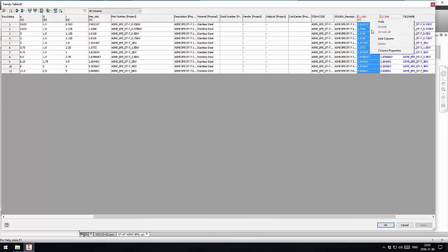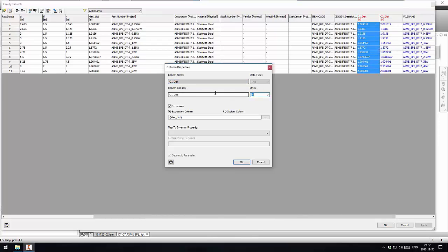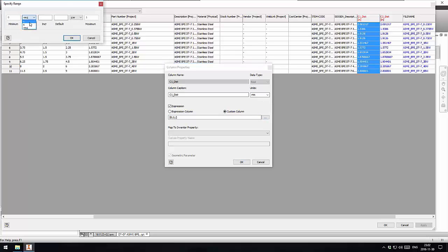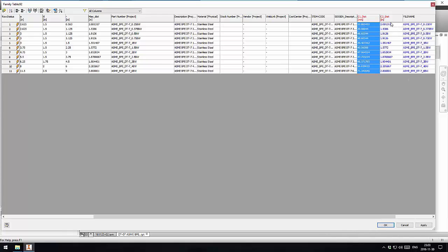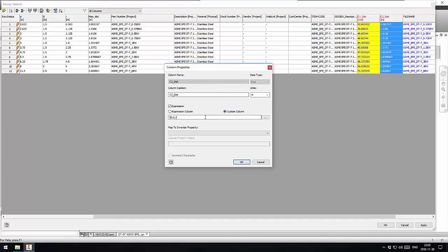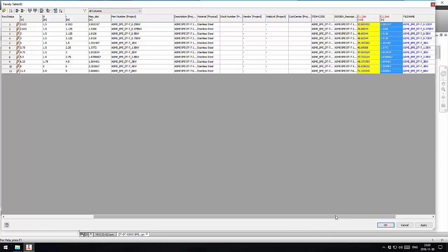Even though the value is going to be in inches, we want the user to enter millimeter units. And we're going to say that's custom, greater than 0, 1 millimeter increment, where in fact that's not needed. Give me 2 and 3, and then we're going to paste in here. Maximum is actually going to be max distance, and the default value is going to be max distance. And I'm going to copy this into my second one, and we still have one problem.